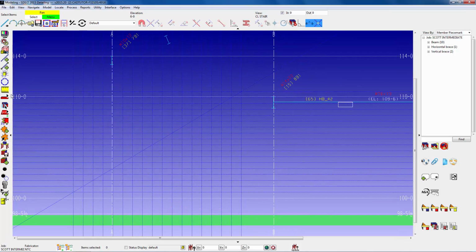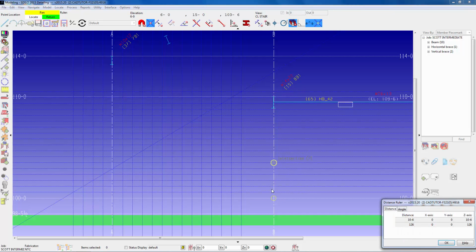So another check here, we can use our ruler. From there to there is my 3 foot. From there to there, my 100 elevation is my 10'6". Picking again as another check dimension from grid line B, there's my last riser, my last nosing, but my stair actually starts over here, which is 19'6" over. So that's correct.